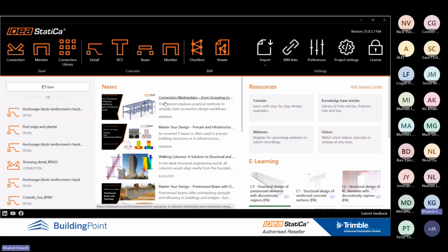But here, since we are dealing with the corbel, we know that we cut the corbel and this column is continuous. So that's why you can change the anchorage type at the end or beginning of the section. Here I just apply the continuous reinforcement by selecting these 3 reinforcement. If I go back to the 3D real view, I will change the continuous bar, because these bars are continuous, to the continuation of the column. So that's why here you can see how the reinforcement is presented.